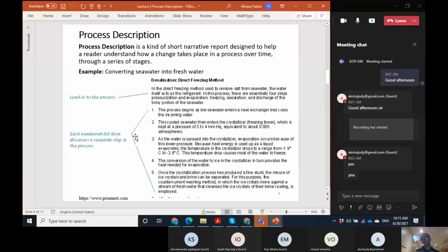A process description, in fact, is a document. It's a narrative document. It's just a text, okay? Mainly text, of course, maybe with some simple formulas or some figures, but it is mainly text. It's a text or narrative explanation of the process and the control requirement, like the sequence control. It is not a PLC program. It is not a logic diagram. It is not a control circuit wiring, hardwire control system.